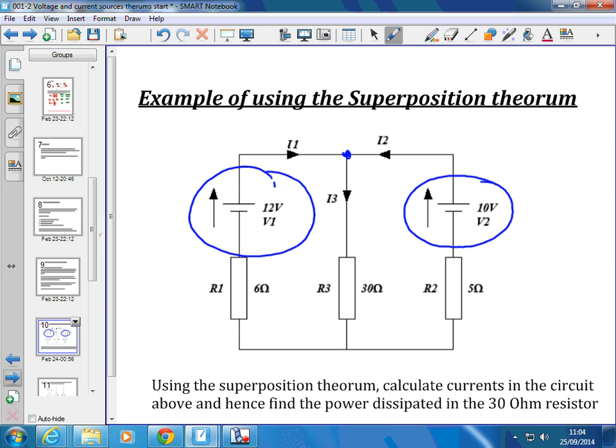So if I2 comes out as negative, you've properly applied Kirchhoff's laws throughout all your calculations. It means that you had the arrow on the wrong way when you started. You made the assumption it was going that way, and under these particular circuit conditions, it's actually travelling into that battery, and effectively it's being charged. Okay? But you have to be consistent. As you go through the process, we've got to keep these arrows the way they are.